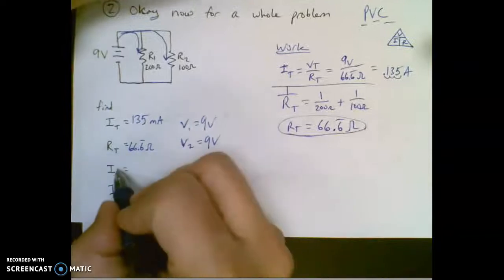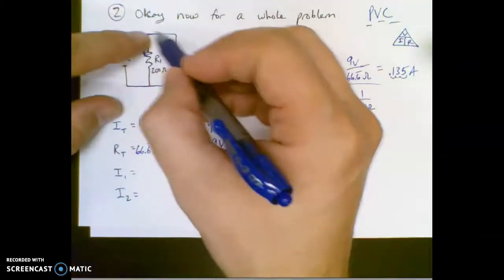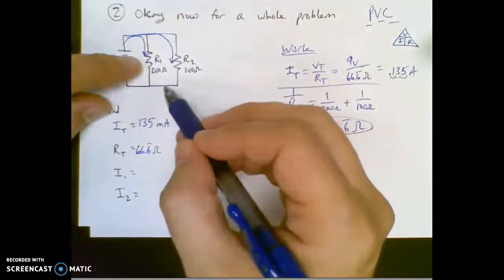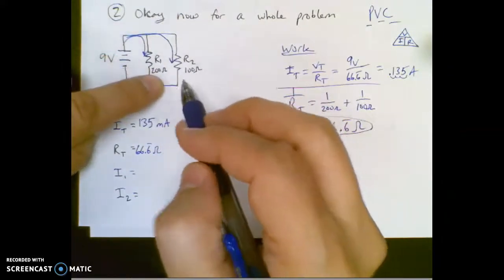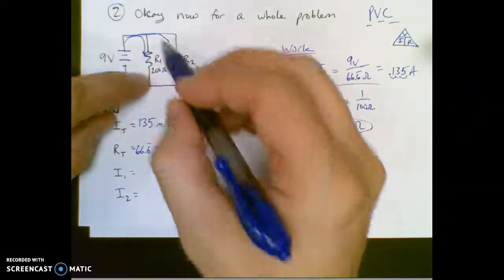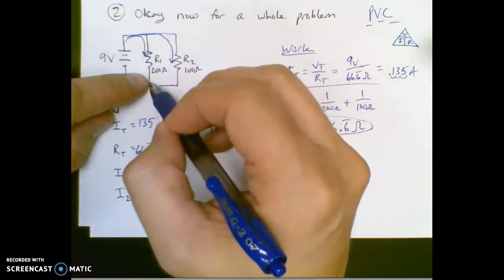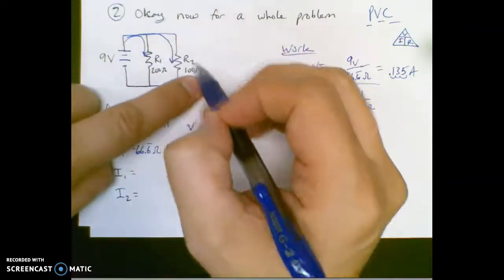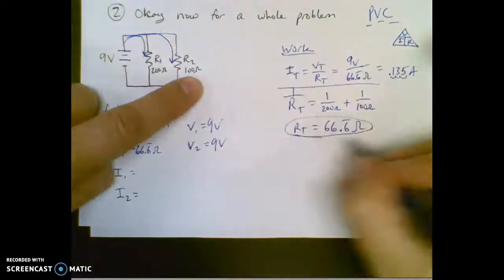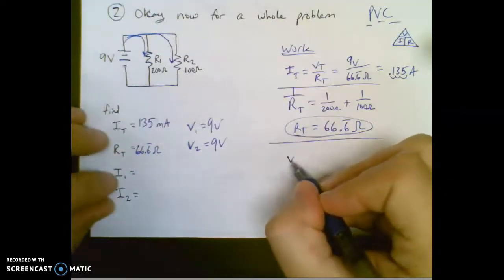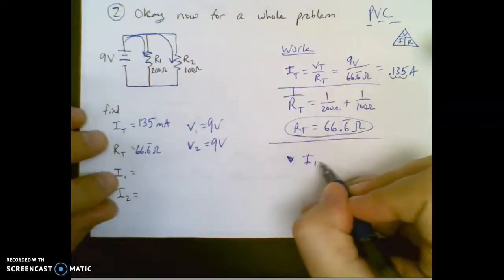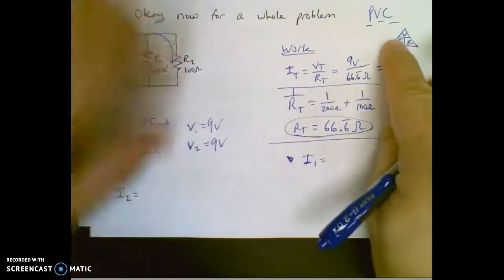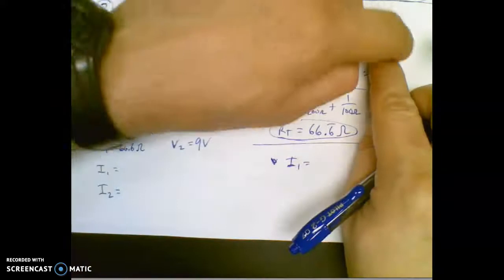All right, now if I want to find the amount of current, remember how I said people are going down these stairways differently? I would expect more resistance, so think of skinnier stairway. I would expect a slower current or less current going down here, and I would expect more current going down the wider hall, the wider stairwell. So when I go for I1 equals, remember cover this up, I is V over R.